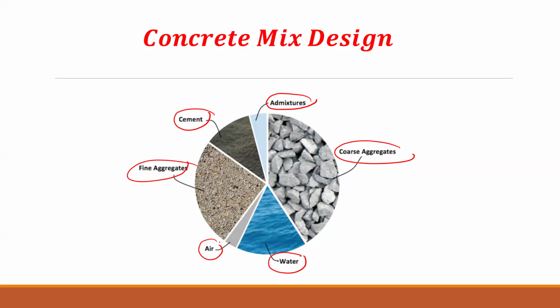We discussed something last week regarding sulfate reaction with concrete. If we place concrete in a sulfate environment, that reaction makes the concrete swell and expand. So we need to provide space to expand, otherwise the concrete will crack, isn't it? And also in a freezing environment, when water freezes, it will expand.